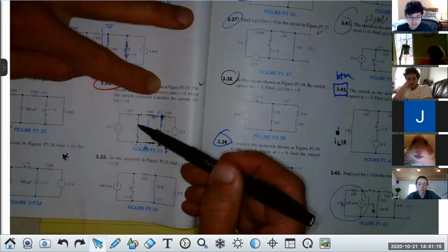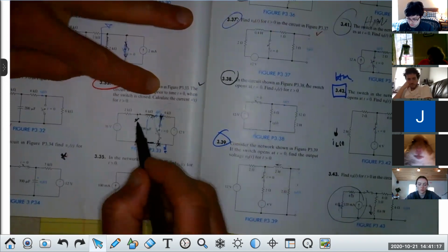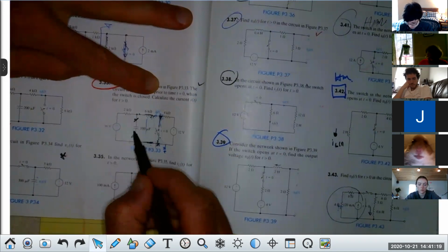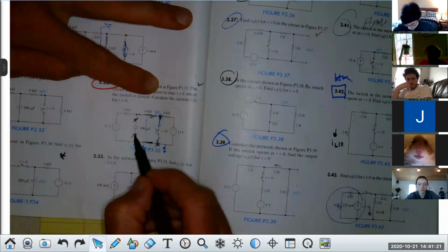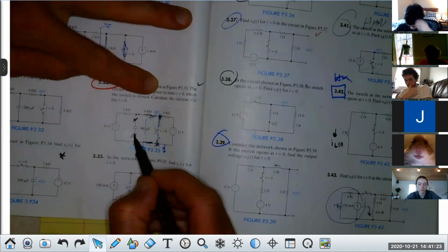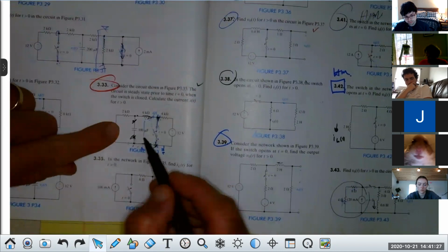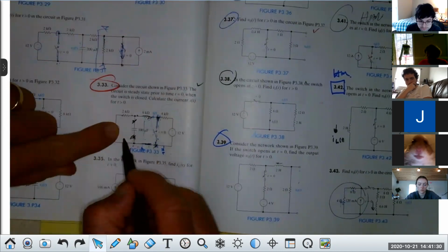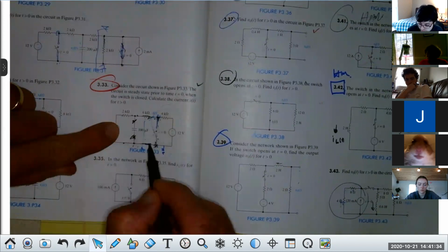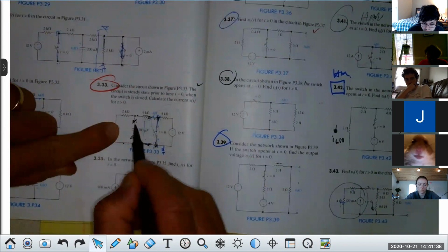For the capacitor, the points that we're calculating, we remove the capacitor and calculate the Thevenin equivalent resistance where that capacitor was. Remove it in your mind and short that. This 2K goes to ground, right? That 6K goes to ground, right? Aren't both of those in parallel?